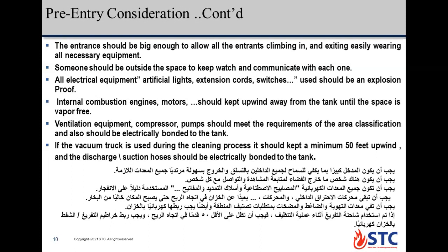Internal combustion engines and motors should be kept upwind, away from the tank, until the space is vapor free.